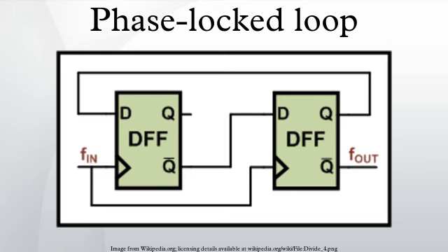The oscillator generates a periodic output signal. Assume that initially the oscillator is at nearly the same frequency as the reference signal. If the phase from the oscillator falls behind that of the reference, the phase detector changes the control voltage of the oscillator so that it speeds up. Likewise, if the phase creeps ahead of the reference, the phase detector changes the control voltage to slow down the oscillator.